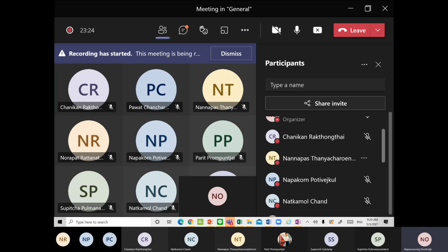Or it may happen that the same operator measures the same part different times, but does not have a good enough work instruction, steps, or measuring method. So they may use slightly different methods at different times, and that may cause variation among the different times that the operator does the measurements.